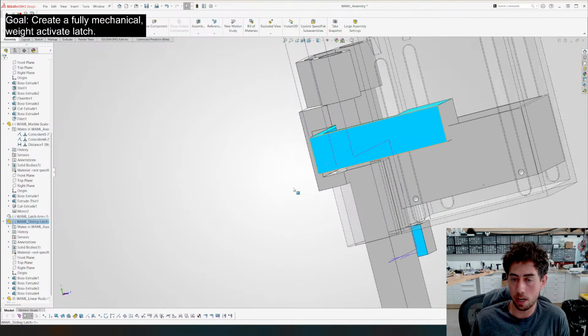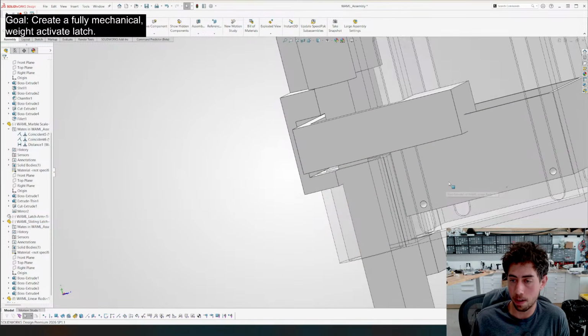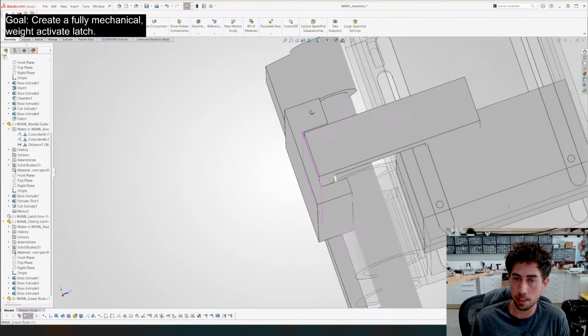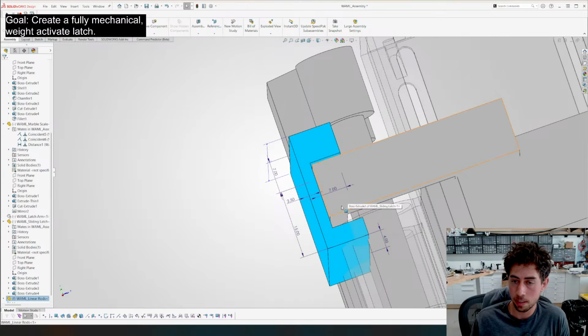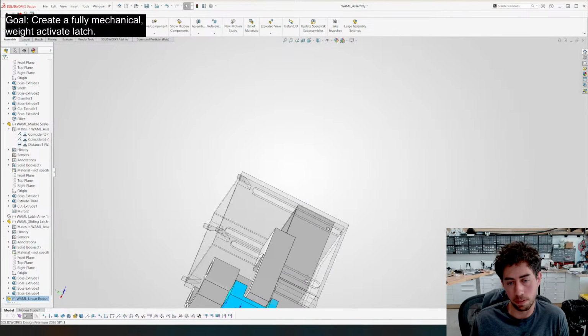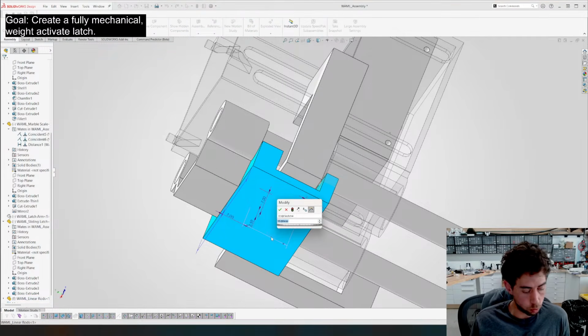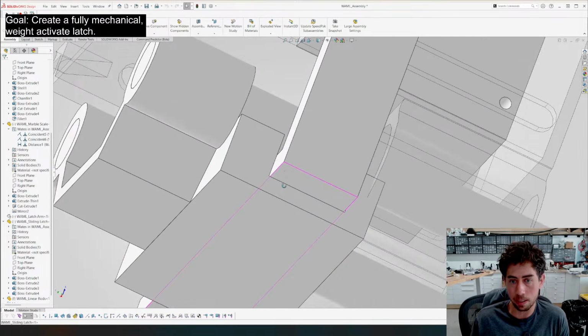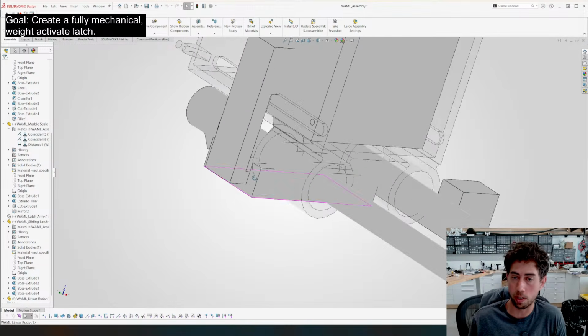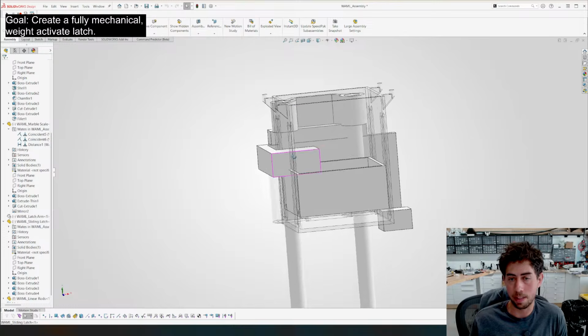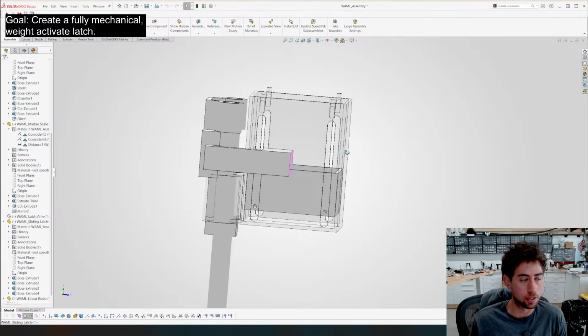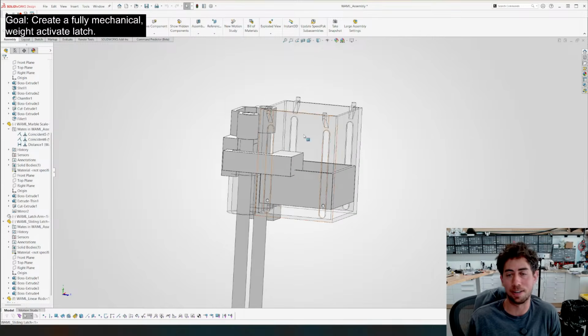This is 12. The thickness for that is going to be this, and that is, I think, this 15. So I'm going to make it 12.35. So there's a little bit of clearance, not too much. You don't want it to wiggle too much. There's definitely a balance. Sometimes if it wiggles too much, it just binds and it's over at that point.